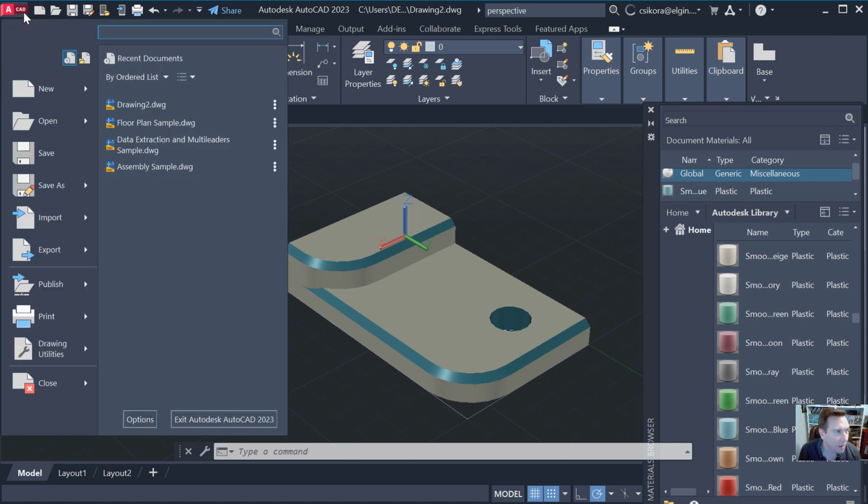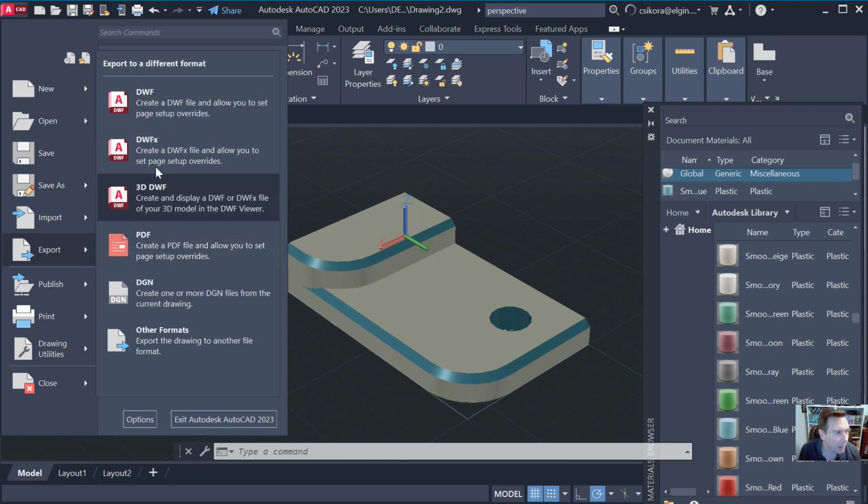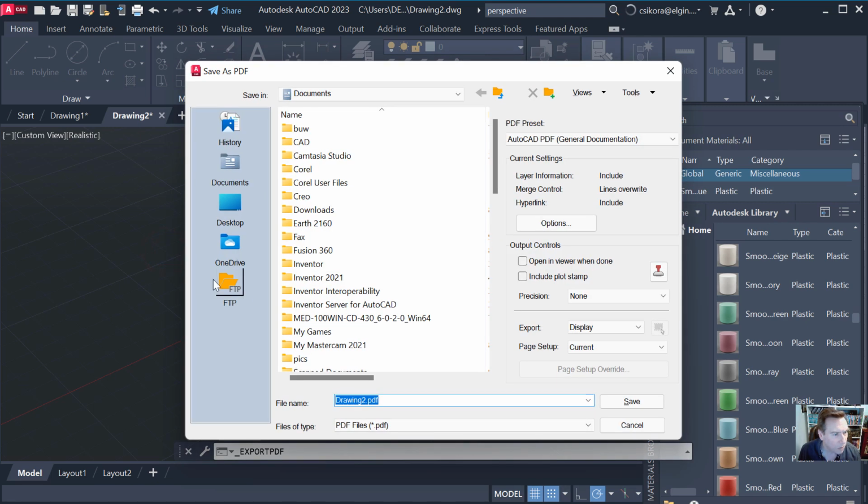Those of you in my class you can now go to the AutoCAD up here, or ACAD, go to Export, and you'll find Create PDF. Now when you select the PDF option here, you could give it a name. So in this case, this is exercise 1. Or E1. And then the display, we could go to Extents, or you could go to Window. I'm going to go to Extents, and let's hit Save.